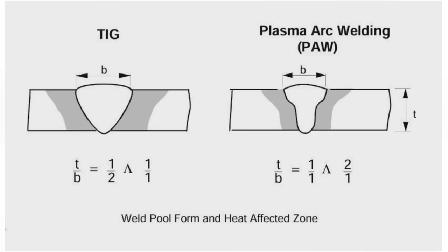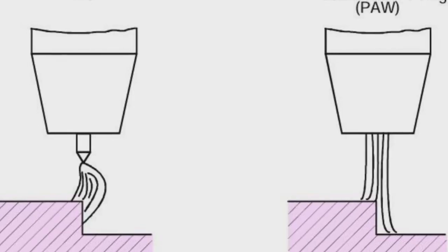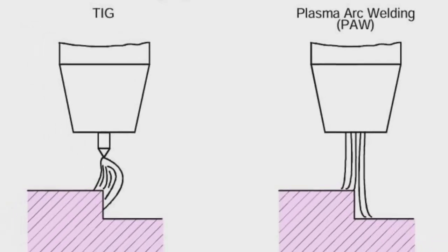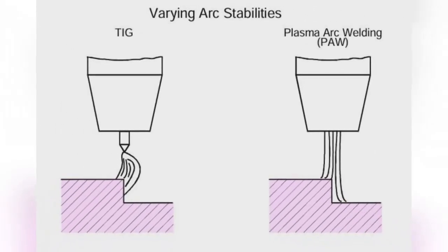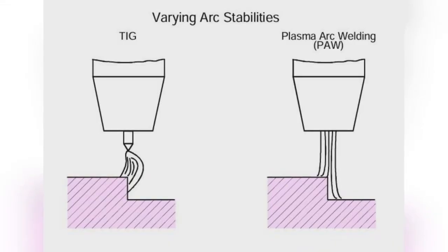The amount of filler metal and the heat input is much lower, so that distortion is less and heat-sensitive materials can be better controlled. The overhead shows a plasma arc weld with a wine glass type of weld penetration. The bundled and strongly constricted plasma stream is stabler than in the TIG process. The plasma arc does not tend to stick to edges and the weld pool.